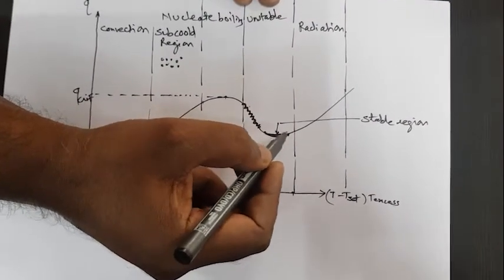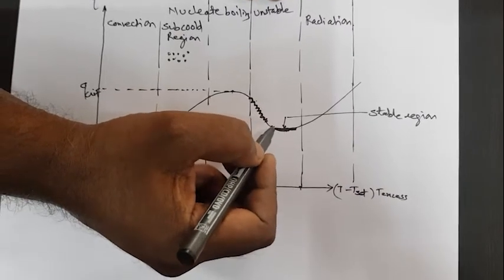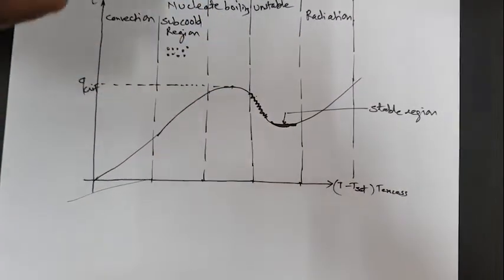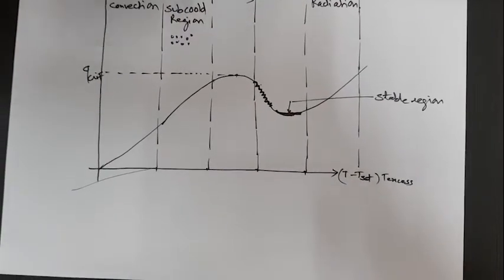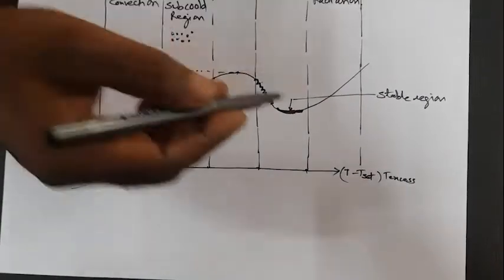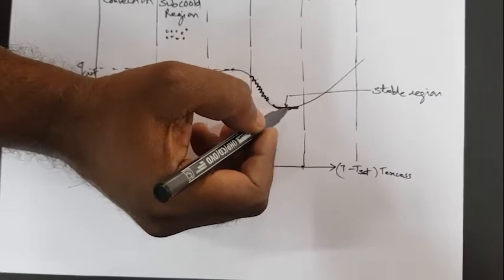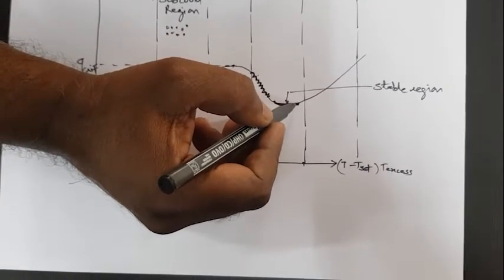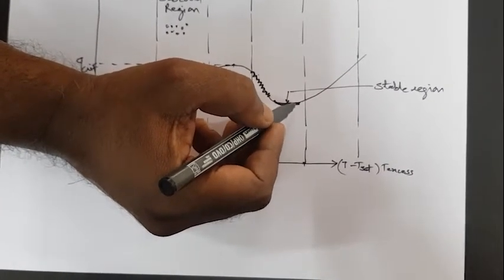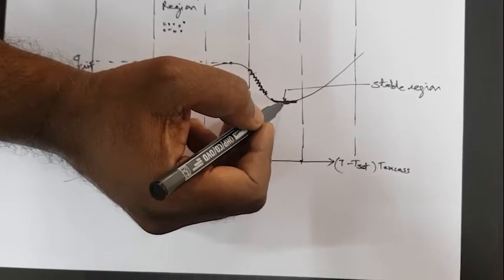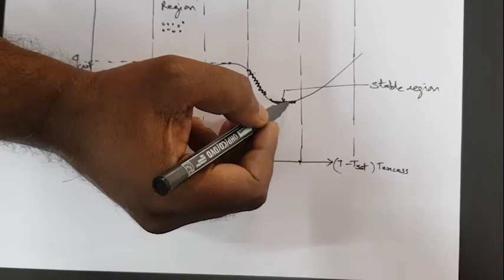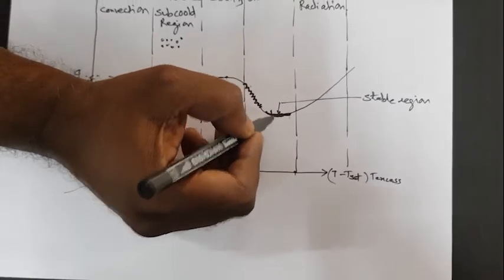Heat transfer now takes place from the heating surface to the bubbles, and from the bubbles to the water. So a constant heating surface area is available, but it is covered by water vapor, and that is why heat transfer is less, whereas it is constant here for some time. From here to here, suppose.